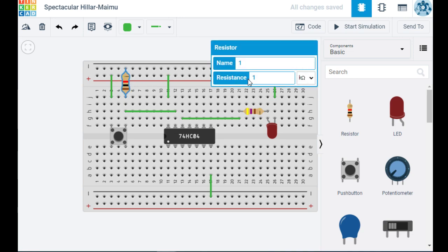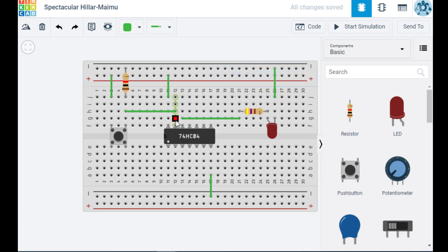And this resistor, how much should it be? I have a 1K here, that'll work fine. A 2K works fine, 2.2K, 2.7K, 5K, 800 ohms, whatever. When I first learned this, I was taught to put a 5K resistor, but I'll be honest, once you start going really high, 5K, 7K, I start to run into problems. But theoretically, you can use up to like a 10K, a 10,000 ohm resistor, and be okay. But when you go too high, you actually do run into problems where there's so much resistance that no ground is flowing through it, or such a little amount, it's not enough for this to work.